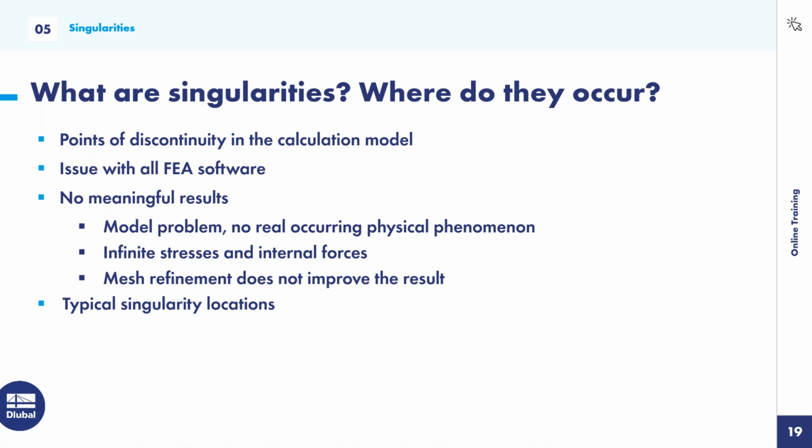And so refining your mesh, or even just increasing the mesh refinement, is not going to improve this result or help at all. It does give you, though, a better idea of the location of that singularity.